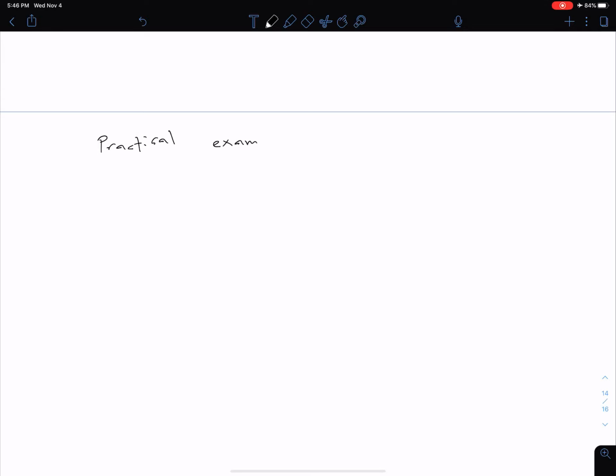Let's say we have some industrial setting, and in that setting we have a radio frequency heater which is being used to heat bags in order to seal them. This RF heater is in this factory, and a typical frequency for this would be 27.12 megahertz. We can relate this back to what we talked about in our high frequency unit. If we look at our frequency allocations, we can see that this falls into one of our ISM bands. Remember, ISM was industrial, scientific, medical. These are really narrow bands at certain frequencies.